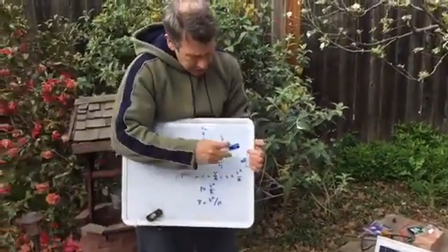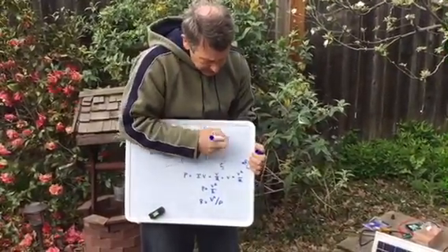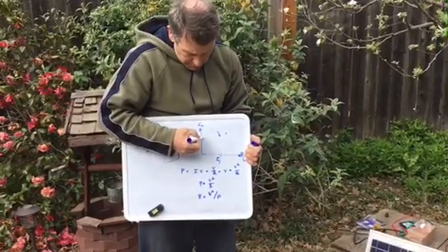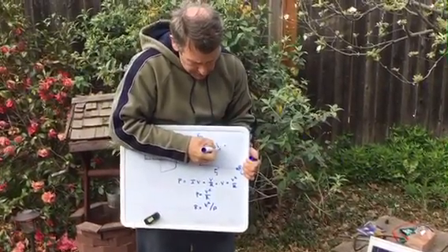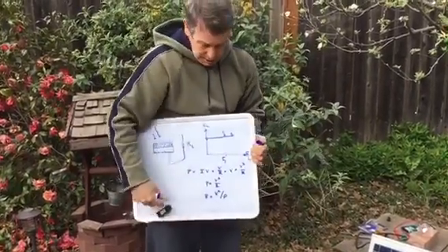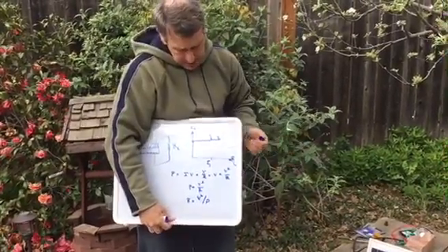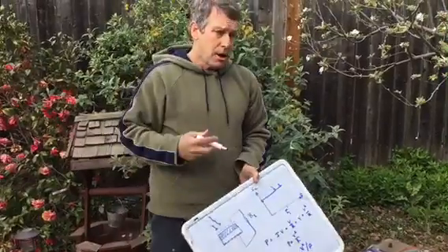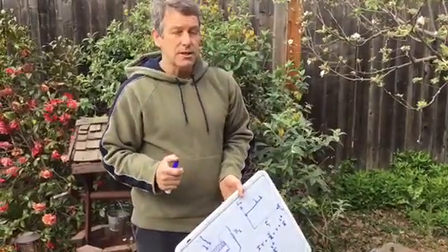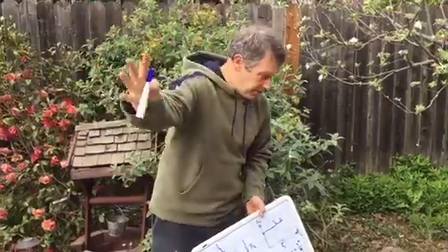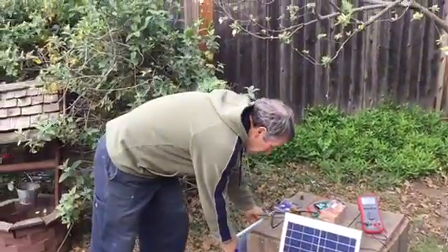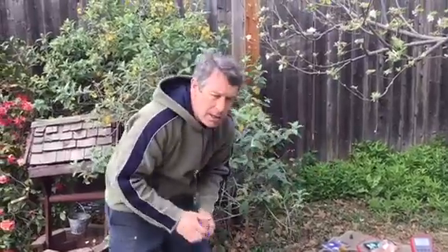Okay, so then I'd have another point here like this. And ideally, if we had an experiment, we could do a bunch of different resistances. We're going to get the same current until the resistance gets really large, until the resistance gets way out here like this. So as I was talking about earlier, a great way to think of a PV generator, like this generator, is a constant current producer given a certain level of radiation coming in. All right, so we'll get back to work on that in just a minute.